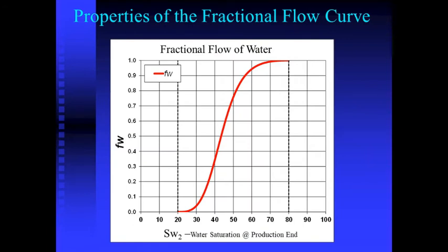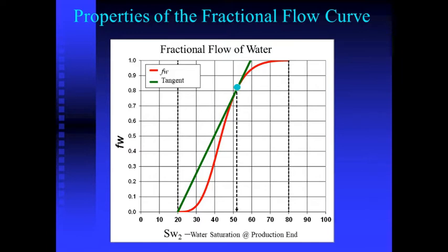If we choose one of the fractional flow curves that we saw in the previous slide, we can study, through graphic analysis, the equations that go together with the frontal advance theory. In this way, if we draw a tangent to the fractional flow curve, a tangent that starts at the point of irreducible water saturation, the value of water saturation at the contact point defines what we know as the water saturation at the breakthrough, that is, at the arrival of the waterfront to the production end.